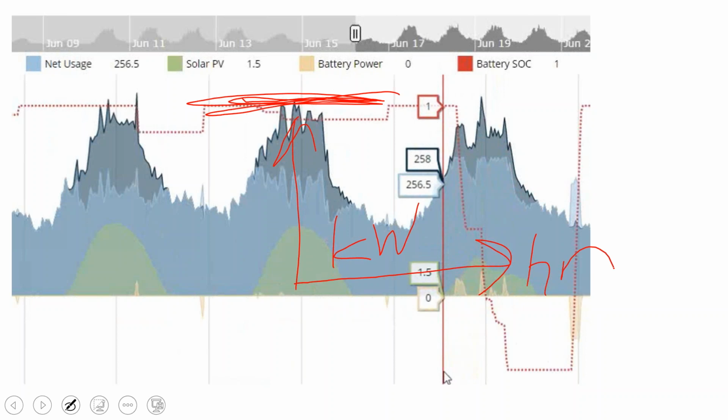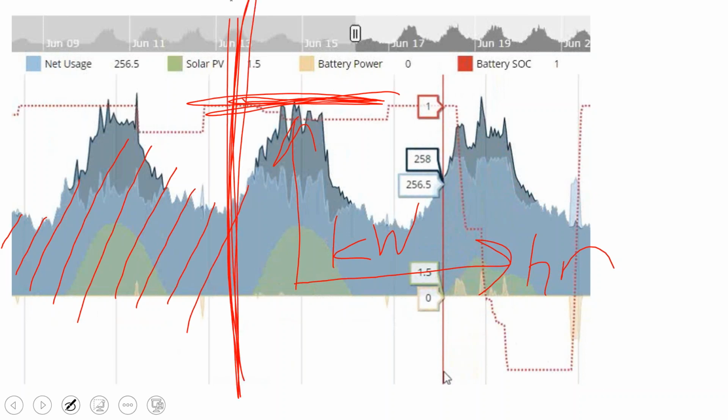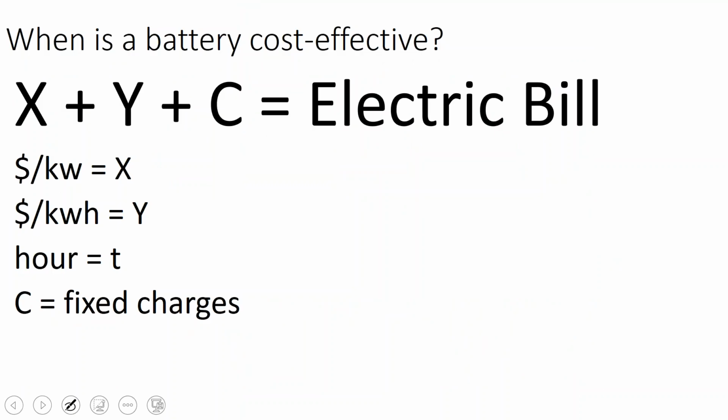In other words, with residential rate structures, you're more commonly billed for the volume under this curve, whereas with commercial bills, maybe the volume under the curve is only half the bill, and the other half is their maximum peak over the billing cycle, over a 30-day window. What is their maximum sustained, tip-top 15-minute building demand over the course? So if this little peak is only for 5 minutes, what they do is take your 15-minute average. And so to put it into a formula,